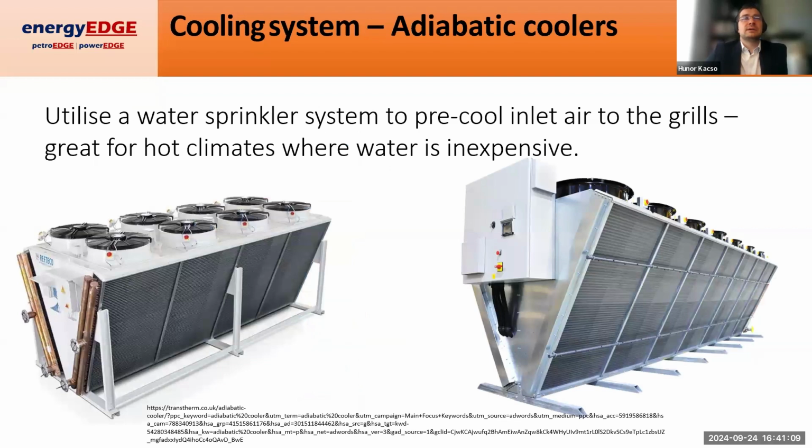So on some systems, and this is especially used in relatively large electrolyzer systems and in relatively warm or even hot climates, we're seeing adiabatic coolers. And what is an adiabatic cooler? On the left-hand side, you can see a normal air blast cooler. On the right-hand side, you can see an adiabatic cooler. The difference is that the adiabatic cooler has a sprinkler system. You can see these lines here, these are sprinklers.